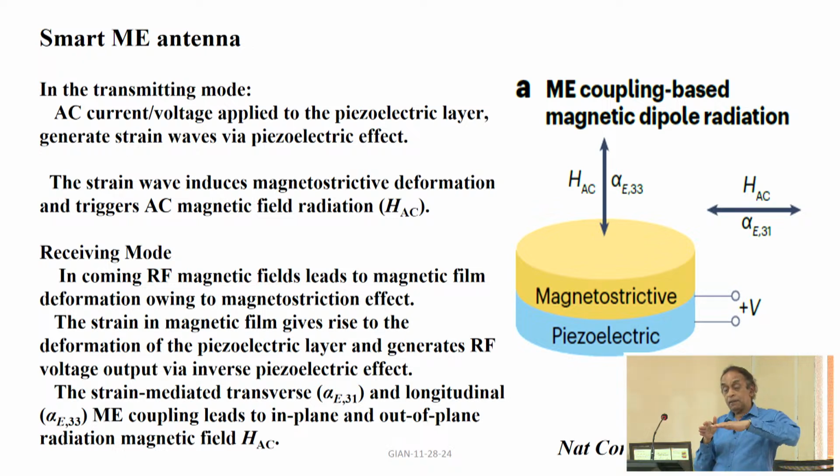It can be bending resonance, or it can be longitudinal or radial acoustic mode, and this would happen at kilohertz, hundreds of kilohertz, if the sample is 2 centimeter long. But for ultra miniaturization, you can make it as small as possible, just a few tenths of a micron. So, smaller the dimension, higher the frequency. So, you have a miniaturized antenna that can be used at 100 megahertz or several gigahertz.